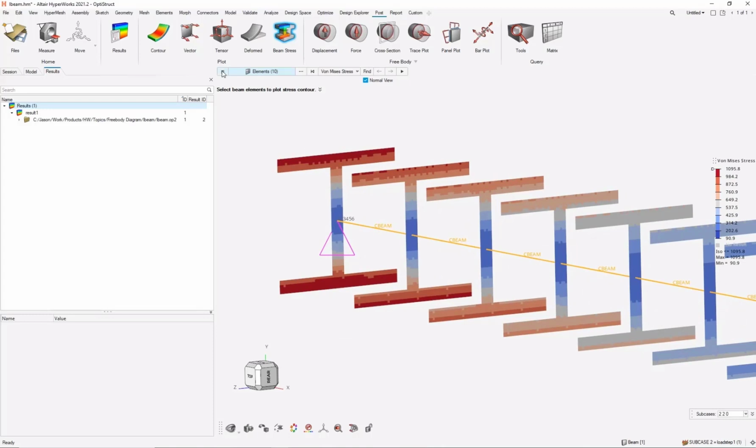We can go ahead and go to the advanced options and mesh mode. So it's creating a new contour based on coarseness or fine. Fine is going to go ahead and remesh that, do the calculation, and create a bit of a finer mesh. And we can also do a contour on element or nodal type. Nodal will give you a bit of a smoother result.